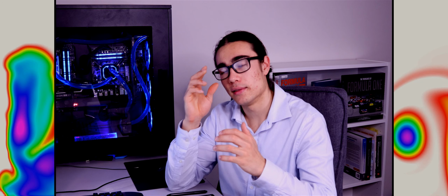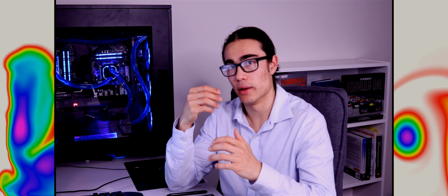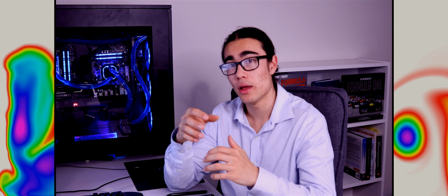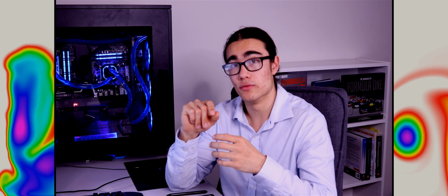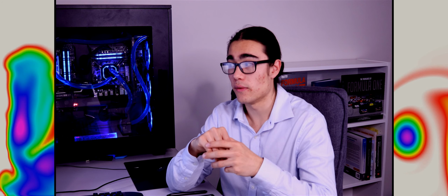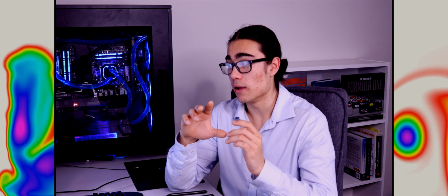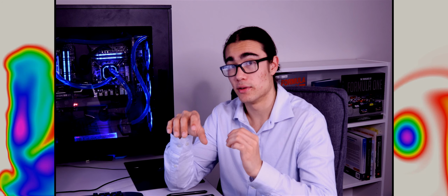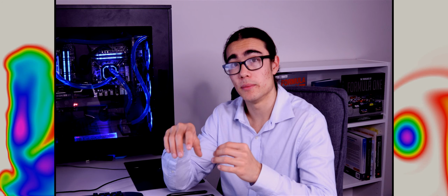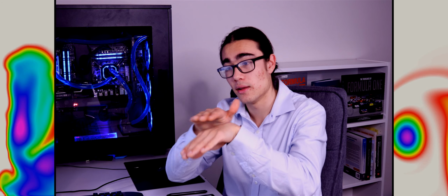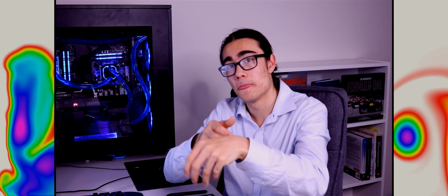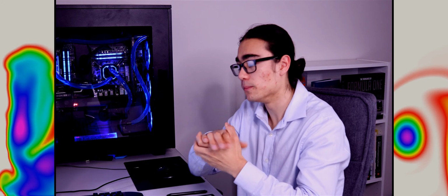And so I said before, let's assume that we're laminar flow and we're on the very edge of tripping to turbulent. Well, provided that the surface finish is the same throughout and nothing's changing, if there's one side which is going to trip to turbulent, it's obviously going to be the top side because we're shearing the flow. There's more chance for us to begin tumbling and transitioning into that turbulent flow.